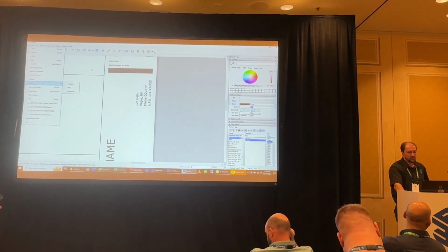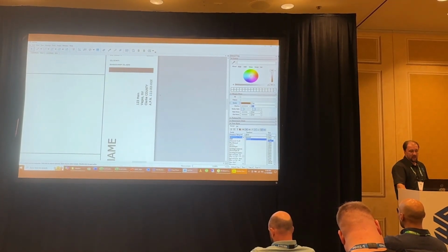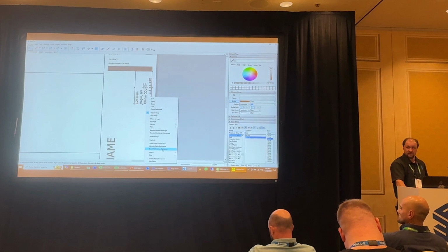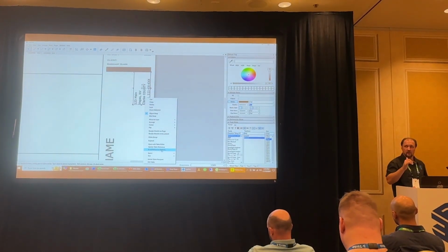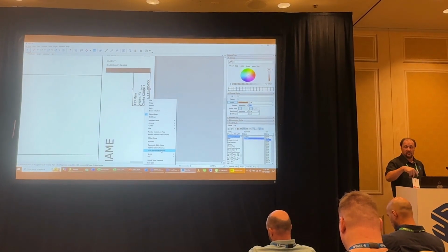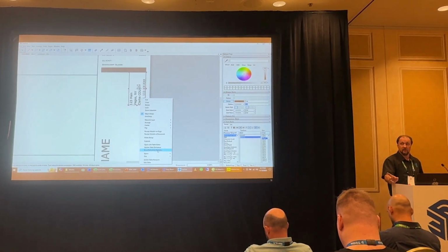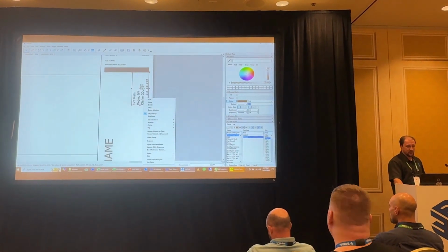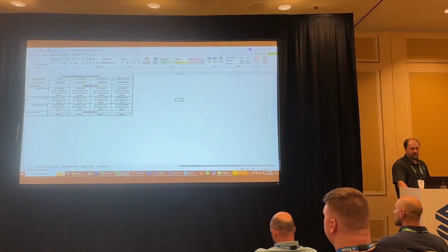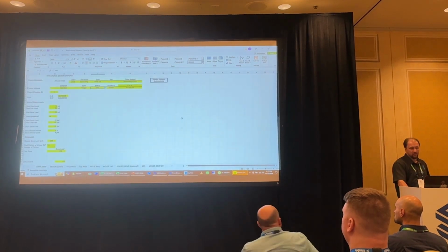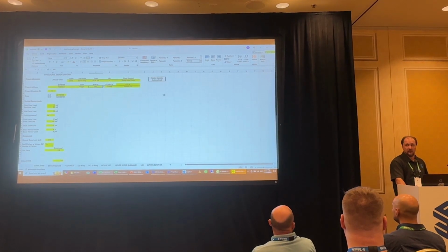Yeah, lots of ways to do it, but if you can get the formatting you like in that table, then right click it and go to your Excel reference options. If you just paste, I'm pretty sure it's just pasting in the table. If you insert that as a non-macro-enabled Excel file, it will talk and reference. It has to be non-macro though. So on ours, I've got this in-between file called Example to Layout. This is not macro. Our calc file will have macros in it, and Layout hates macros. It calls it a risk. It will not import that file.